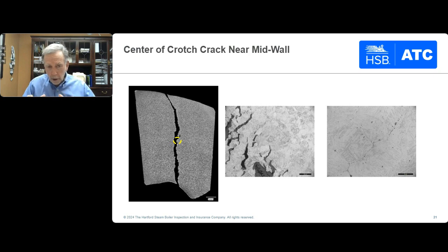Well, as part of the destructive examination on this 10-inch tee and confirmed by other examinations, what we're finding is that in both cases, both in terms of the longitudinal crack at the center of the crotch position, and also in terms of the circumferential cracks that are developing at the girth welds, in all cases, the cracking is creep-driven. It is creep-dominated damage that's forming in these areas in response to the operating conditions. Now, this is surprising for a couple of different reasons.